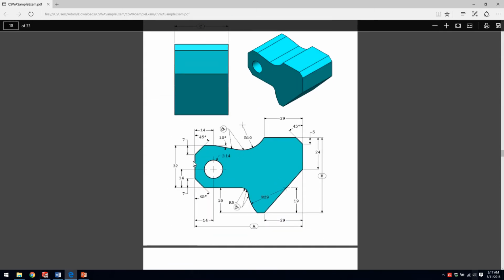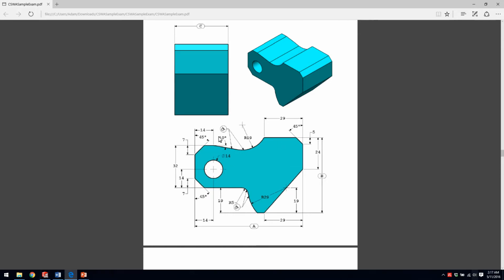And you'll notice in the sketch we have two closed loops. We have an exterior loop that defines the boundary. We also have a hole. So you could, for example, extrude a whole part and then sketch on this face and cut a hole through it, or you could just select this interior to be extruded, but not the hole. So you can make it in one shot.